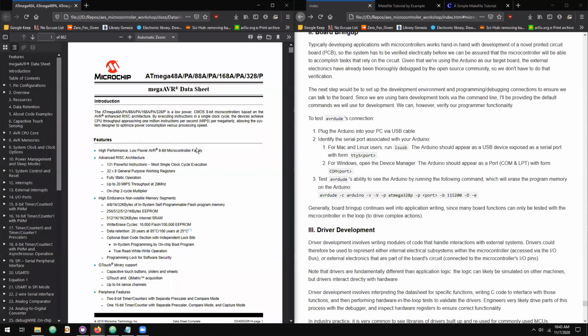So if I ran that command and I get something like /dev/tty.usbmodem, is that the Arduino? I believe so. If you don't have any other serial devices connected to your computer, then whatever shows up should be the Arduino. Okay. And we'll test it right now. So just keep in mind which port it exists on. You'll need the full tty name and the port number. And again, for Windows, it's COM something. So for me, it was COM3. I have no idea what COM port it is on your machines.